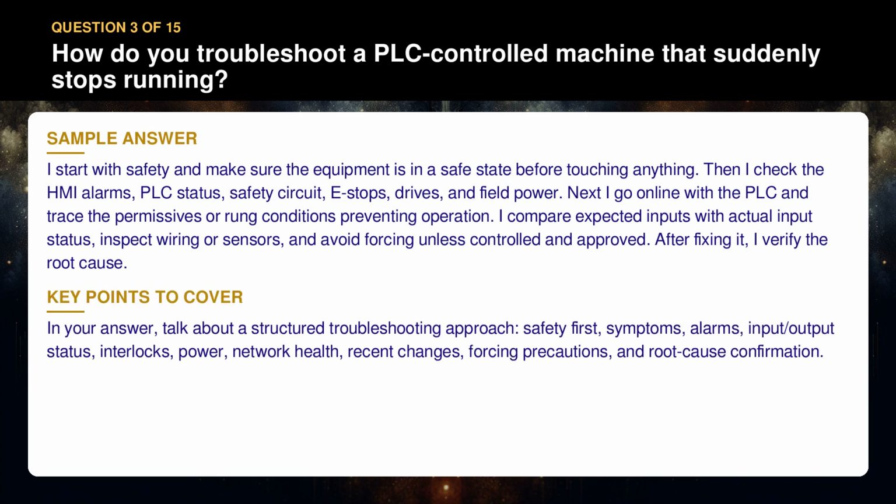In your answer, talk about a structured troubleshooting approach. Safety first, symptoms, alarms, input-output status, interlocks, power, network health, recent changes, forcing precautions, and root cause confirmation.